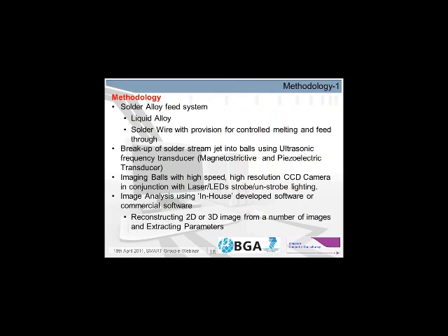Running through our methodology, what we're looking at doing is producing a solder alloy feed system with either liquid alloy or a solder wire with a provision for controlled melting and feed through. We then want to break up the solder stream into a jet of individual balls of consistent size using an ultrasonic frequency transducer. We will be investigating both magnetostrictive and piezoelectric transducers.